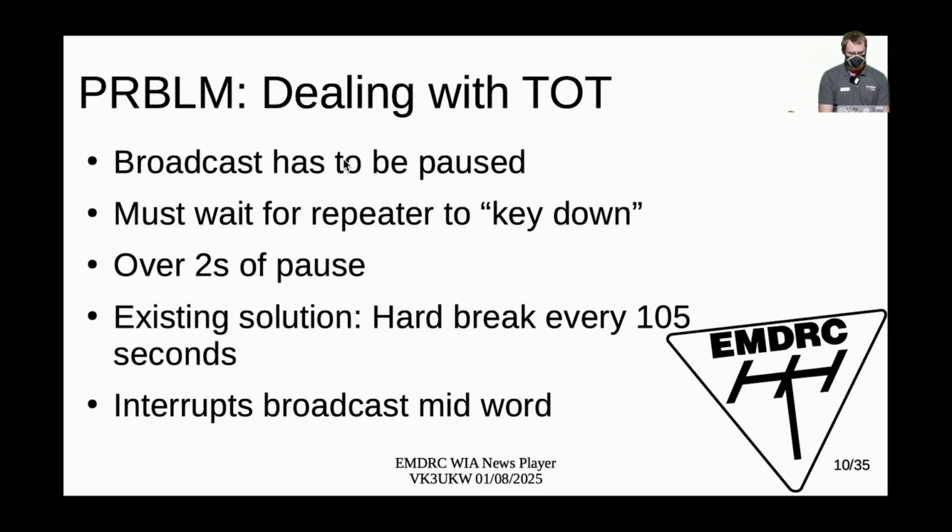With this Yaesu repeater, that's over 2 seconds that you have to pause for it to reset. And there is an existing solution from a group in, pretty sure it's South Australia, where they have a Yaesu System Fusion network with a whole bunch of users. And they also do the broadcast there over the Yaesu C4FM network and frequencies. Their existing solution is that they just chop up the broadcast into, I think, 1 minute and 45 second sequences.